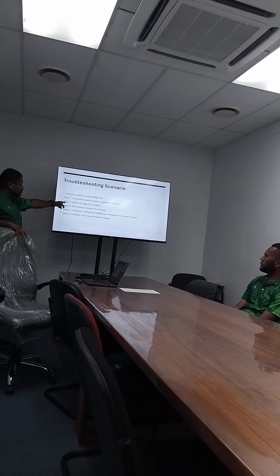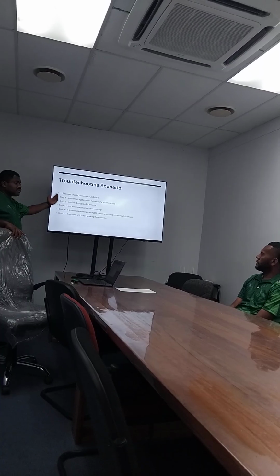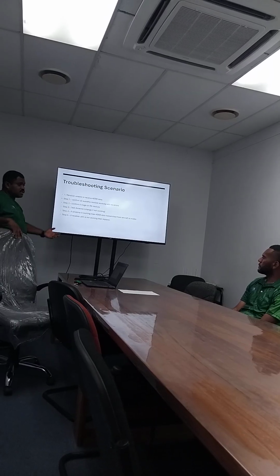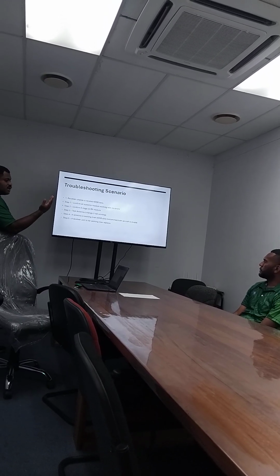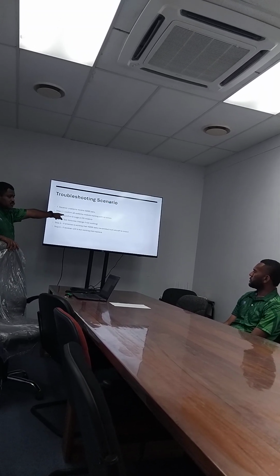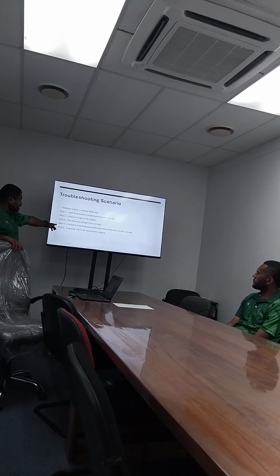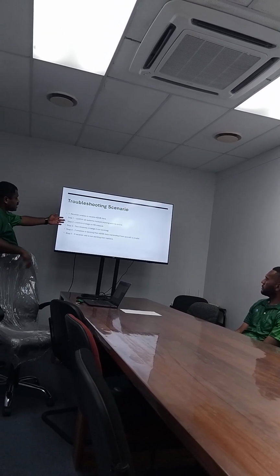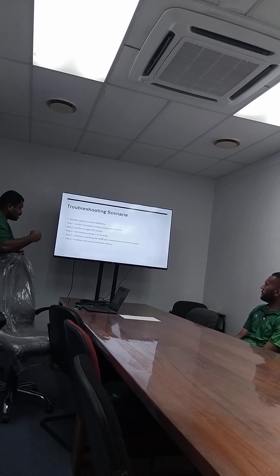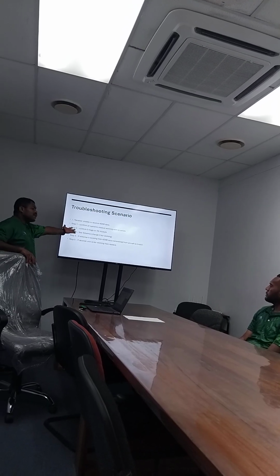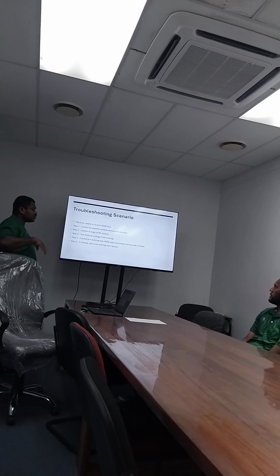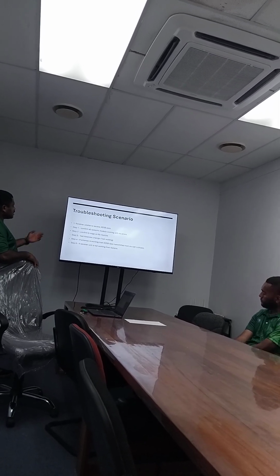If there are messages appearing on the receiver module after we replace the antenna, then we can say that the antenna was not working. If you replace the antenna with a new antenna and there's still no message, then we assume the receiver is not working, and we replace the receiver. If the antenna is working, then the data transmitted from the aircraft is invalid. That means ADSB data is invalid, which is why I got zero messages. If it was valid, then we would have a number of messages received on the receiver. If the receiver unit is not working, then what we do is replace it. So that is a troubleshooting scenario.